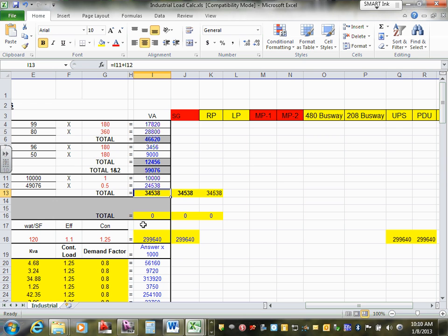Add them up. Number of multi-outlet assemblies, multiplied by 180, non-simultaneously used, and simultaneously used. Add them up, add the total here, and then you apply the demand factor. That's the number: 34.5 kVA is the number for all your receptacles. I need thumbs up, chat, for my receptacles. This is typically what you did with me in the commercial project.